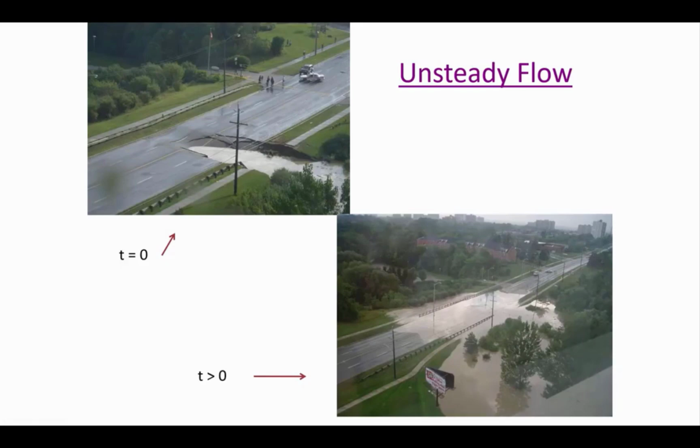and a barrel of a culvert was in place to pass the water. But when there was a lot of water flowing through this creek, the water level rose on the upside end of the creek, and that created a seeping pressure that caused a scour and piping of the soil particles that were around the culvert.